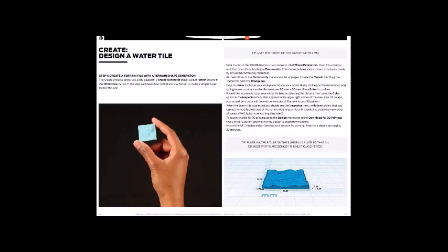We need to remember that when you print with MakerBot, we don't have soluble support material with most of the MakerBot machines, and we have only one extruder. So you need to think about tolerance and how to remove support in a different way. You can see that within the curriculum.